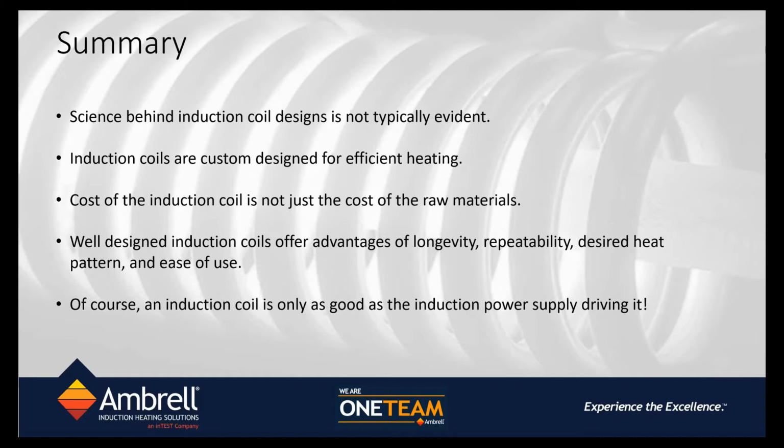All right. So our next question is, what is the ideal frequency for induction heating? And is there even a range? And can you make a comment about induction levitation heating? How does it work with non-ferromagnetic materials? Good question. So there is no ideal frequency for induction heating. Typically, the rule of thumb is if you have large parts to heat, you tend to gravitate towards lower frequency induction heating power supplies.